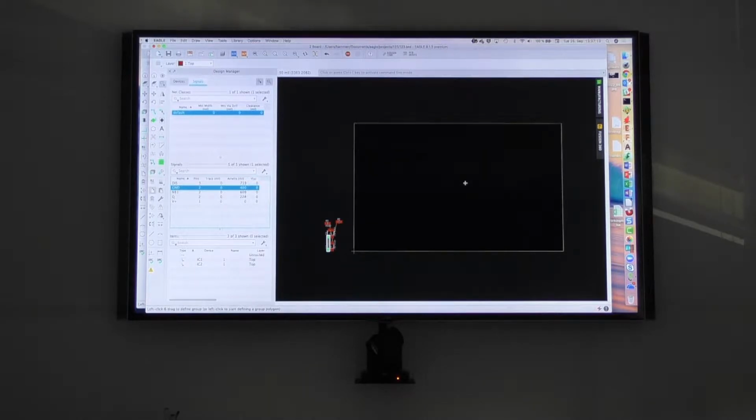That's a kind of, we call it contour detection. If this is displayed in this way, you can be sure that the contour is closed, so you don't have gaps between. Why do we do this? Because we want to work together with Fusion, or think of if you want to have this board produced. In most cases, this is milled out from the big panel. And if you don't have a closed contour, it makes a problem in the manufacturing process. So that's a kind of detection. I can also switch it off if I don't want to have it. There's an option I can show you later.